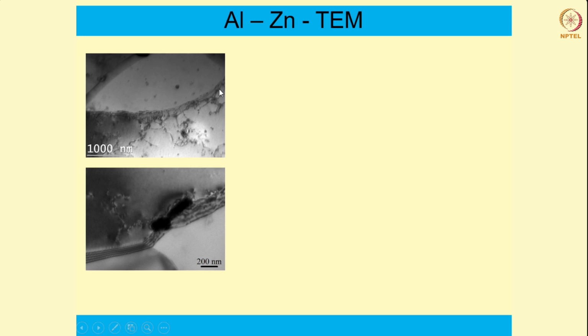Okay, and in that grain, right at the middle, you can see this subgrain boundary forming due to dislocation arrangement. Okay, so now when this subgrain boundary turns into a high angle boundary, then this grain will be divided into two parts and the grain size will reduce. Okay, so that is how the dynamic recrystallization process leads to grain refinement in this particular case.